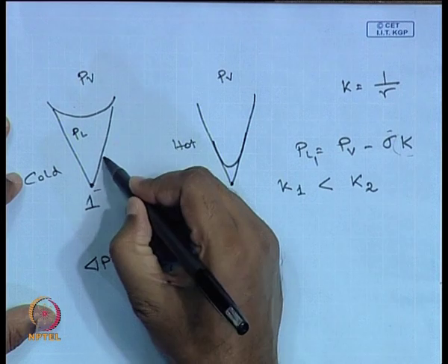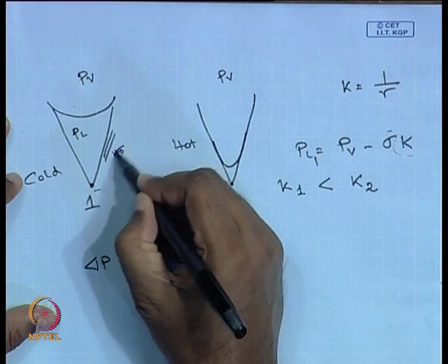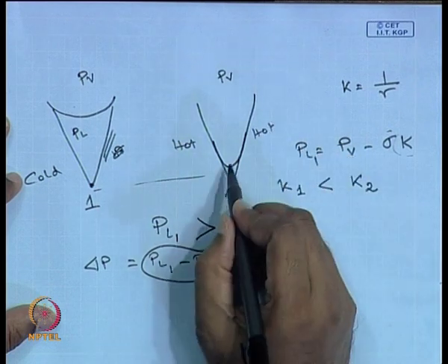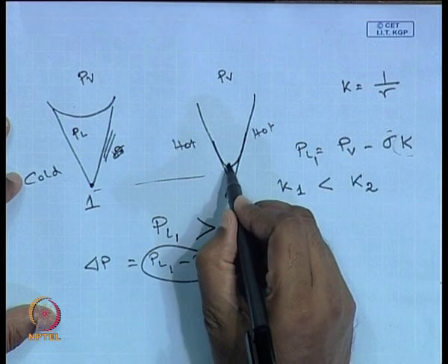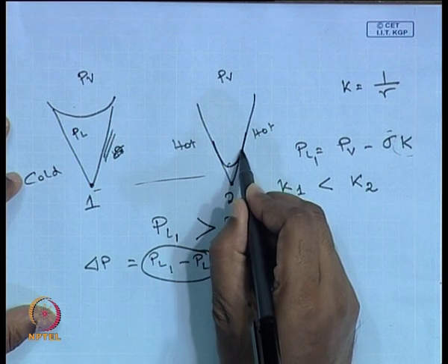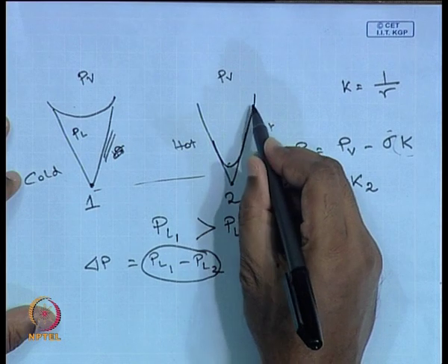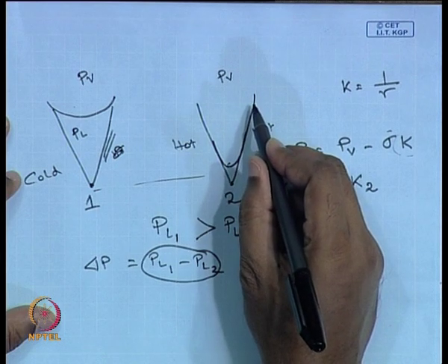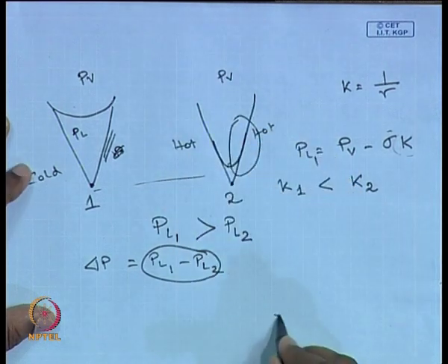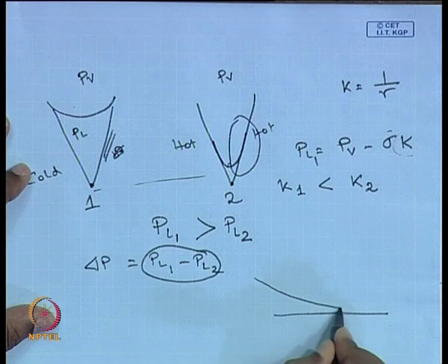These sides are hot, let us say this side is hot. So, the entire solid is hot. So, there is a possibility of evaporation from here as well as from the thin film that extends along the walls of the micro heat pipe. So, if I blow this region up, then I would see a situation which is something like this.